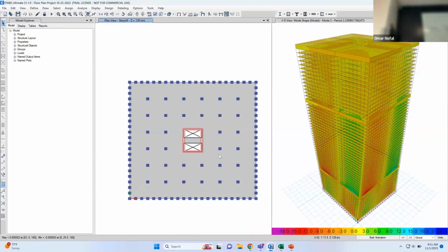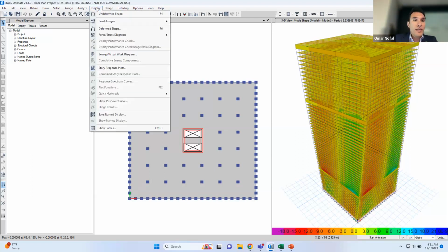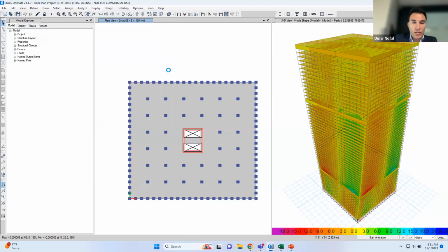Like yesterday, for example, I did the same building, but I did something. I increased the column size from 1 meter to 1.5 meters. And I increased the shear wall from 0.7 meter to 1 meter. Okay, let's see how this impacted the displacement. So let's go to display, same model, same everything. And I just did save as and changed the cross sections. And it was very easy.